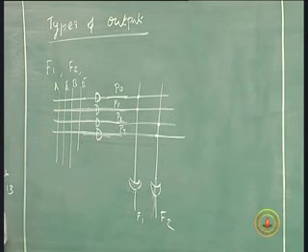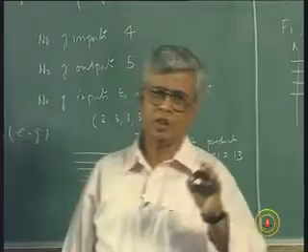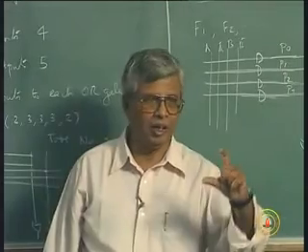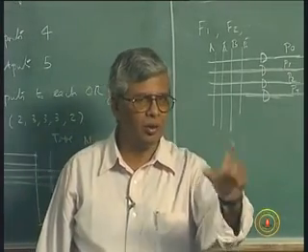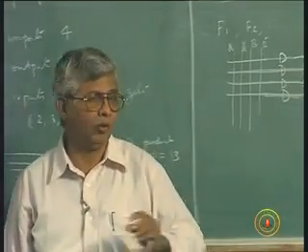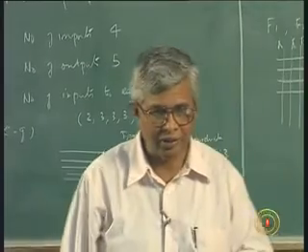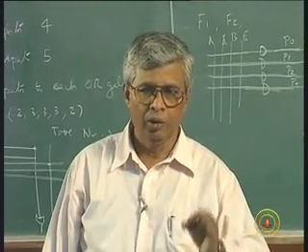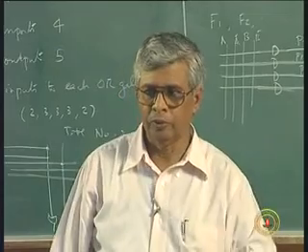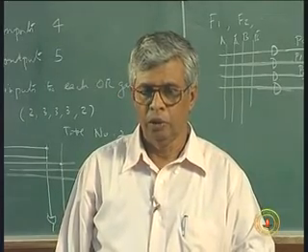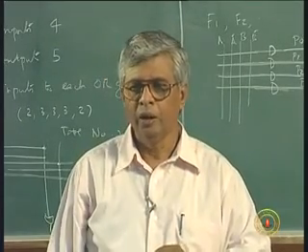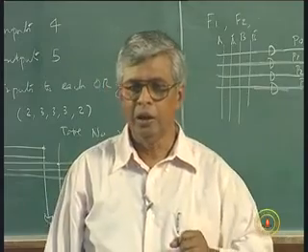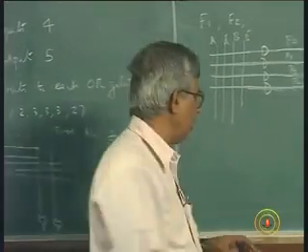This is called, as I already told you, active high logic: a logic in which 0 is represented by the lower of the two voltages. A logic has only two levels, 0 and 5, 0 and 3.3, 0 and 15 if you want it, or occasionally 0 and 1.2 volts, whatever. Low voltage is 0, high voltage is 1. This is active high logic. On the other hand, I may want a situation in which I want active low.